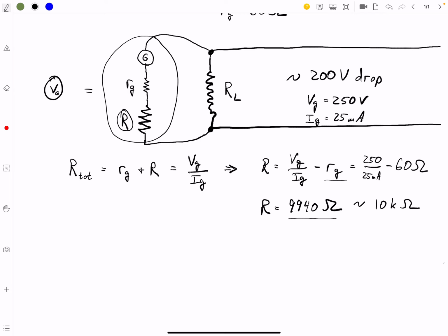Let's go back up to our ammeter. If we're going to select something on here to measure current, we have to come into this range right in here. We're going to be either putting the dial right here or right here. But if we're suspecting that it's 150 milliamps, then we need to have something larger than 150 milliamps. So 250 is the one that we're going to select.